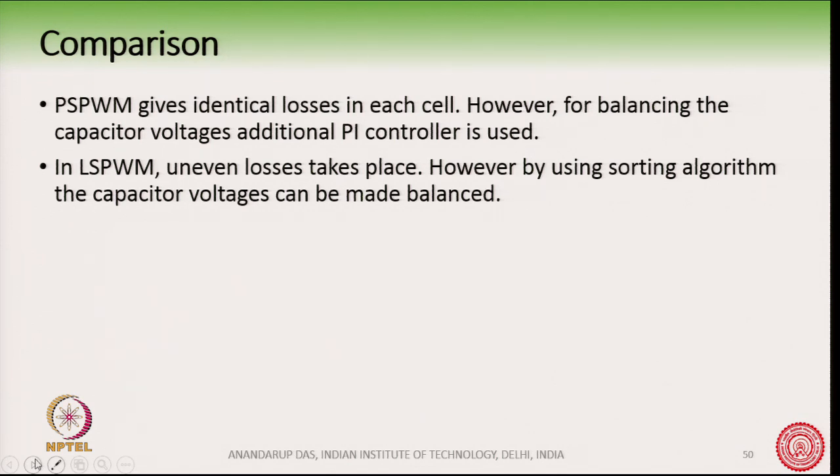Okay. But for balancing the capacitor voltages, because the cells have capacitors on the DC bus and we have to balance those capacitor voltages, for implementing phase shift PWM, we need additional PI controllers to balance the capacitor voltages.